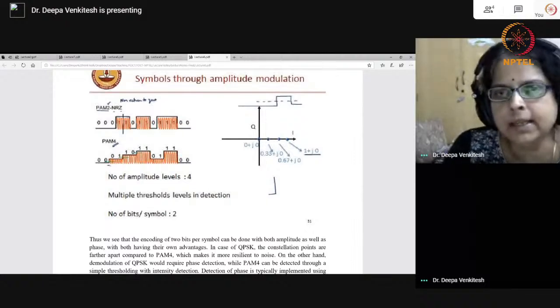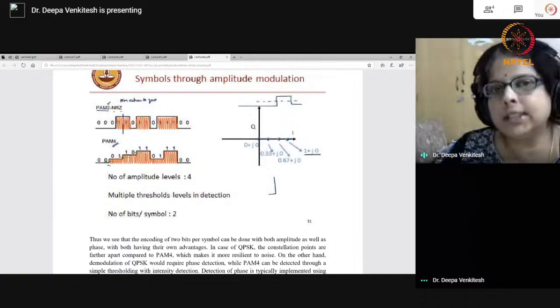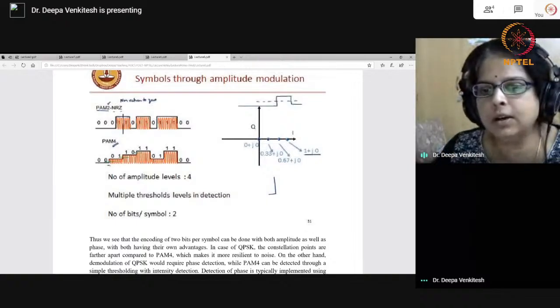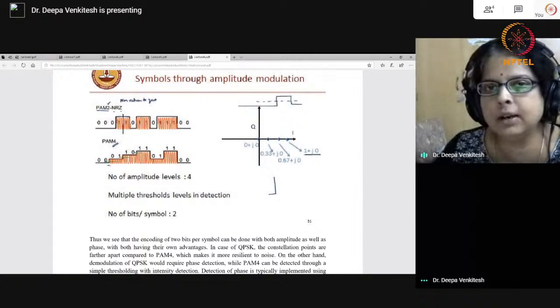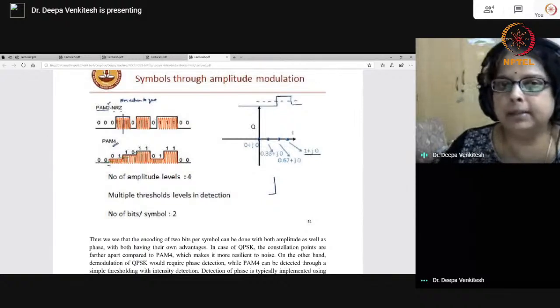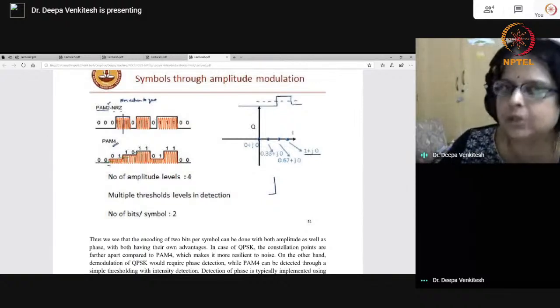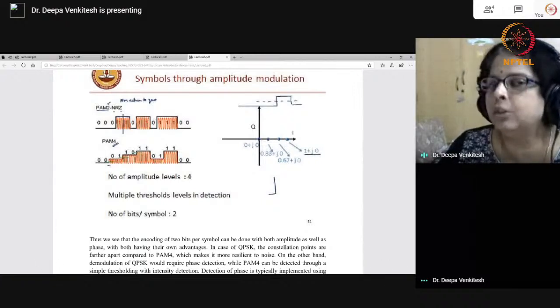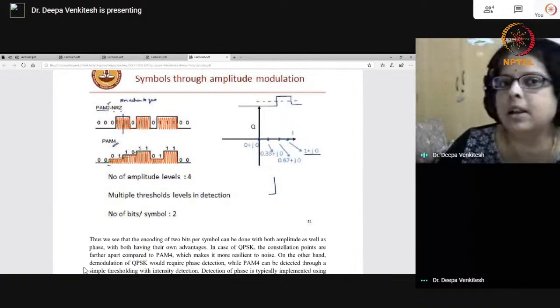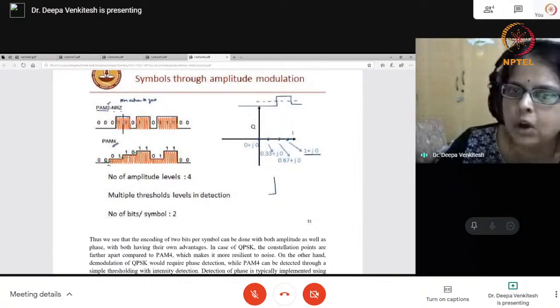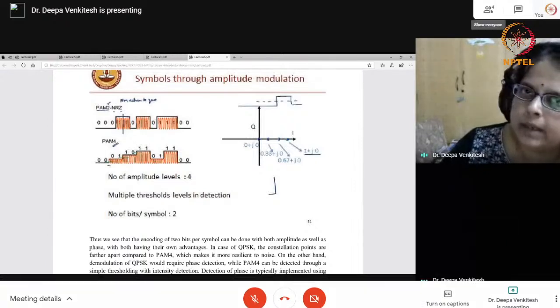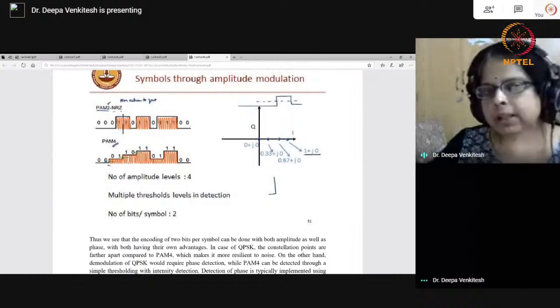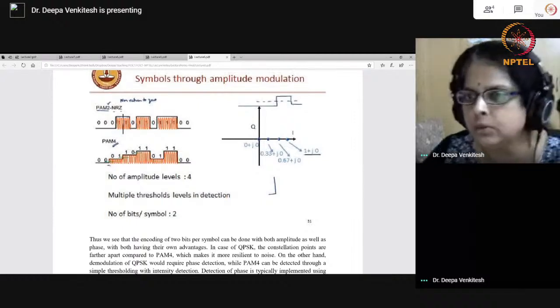But having said that, if I go for very long distance links, I need to have amplifiers in the path because the length of the fiber is large, so I need to keep amplifying. And there are no 1300 amplifiers available today. The technology for amplification in 1300 nanometer is not available today. So for long distance, because the loss is low, I would use 1550 nanometer and deal with dispersion compensation. All that we will talk about in detail during the course.